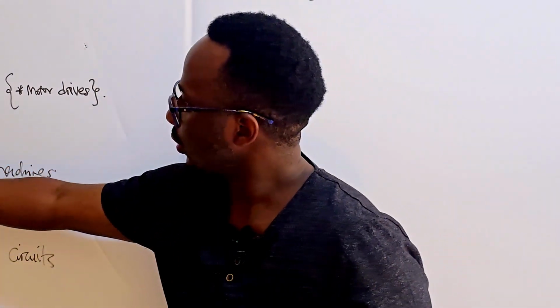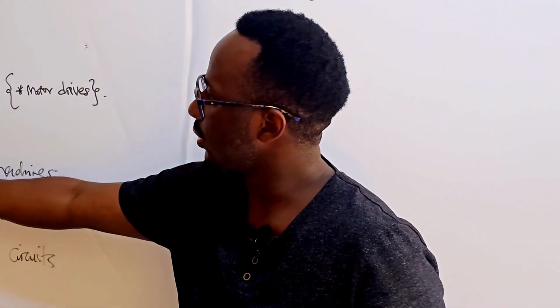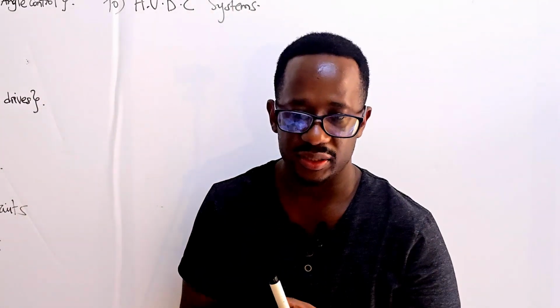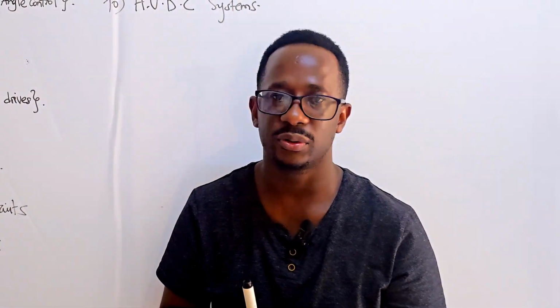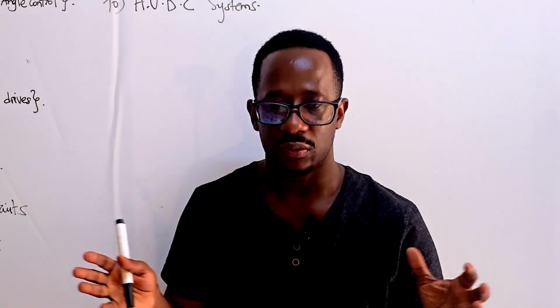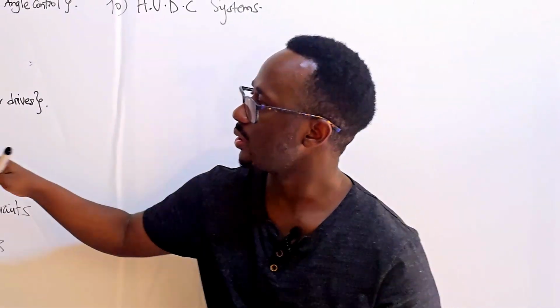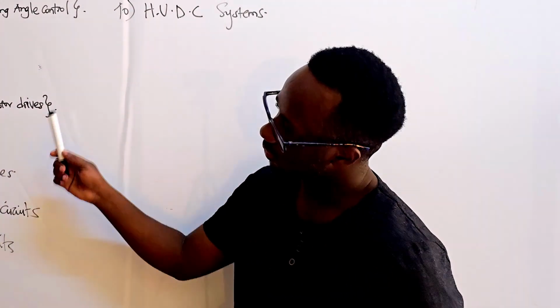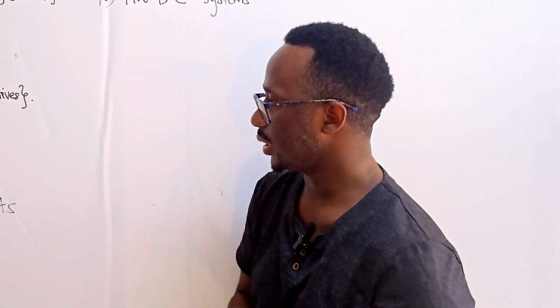So we have what we call solid state relay designing. Instead of having electromechanical relays that create a lot of noise, arcing, and contacts welding shut, we use what we call solid state relays. They are made out of thyristors, triacs, and other devices.